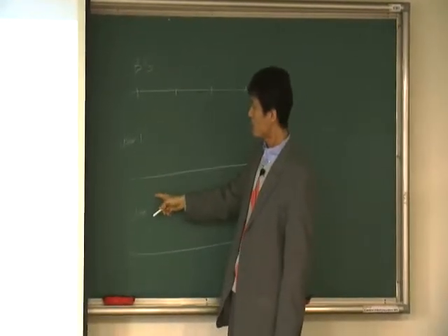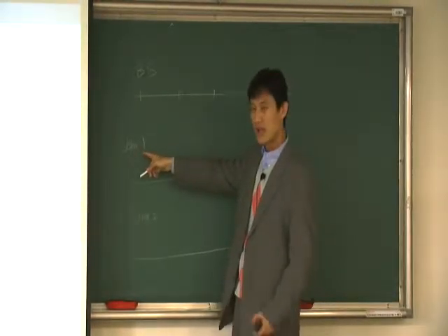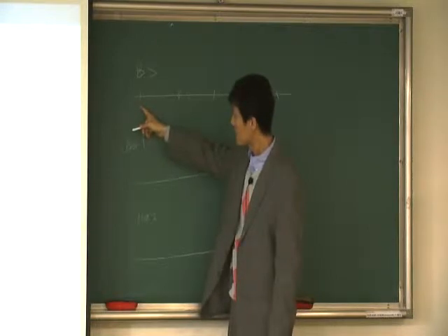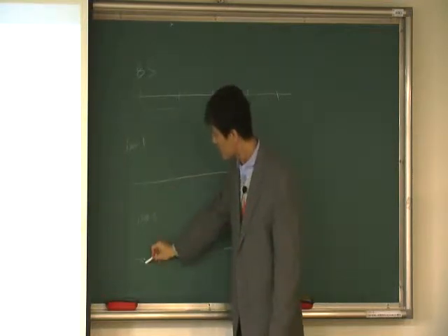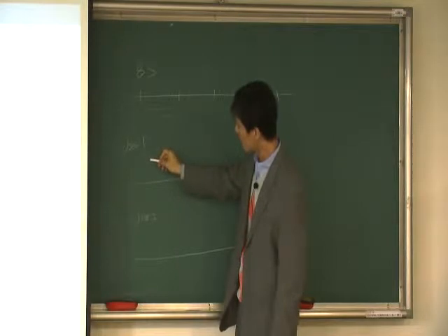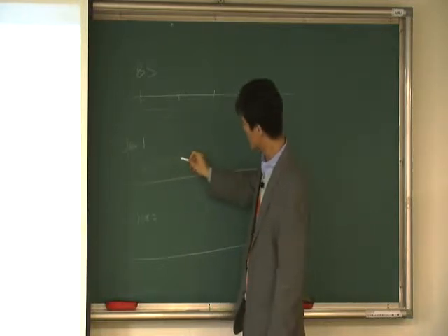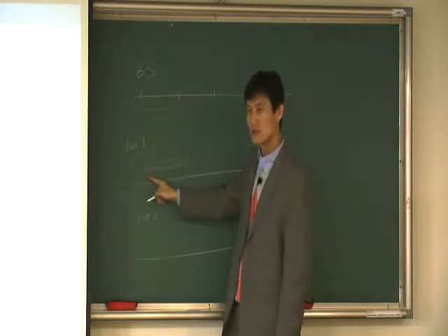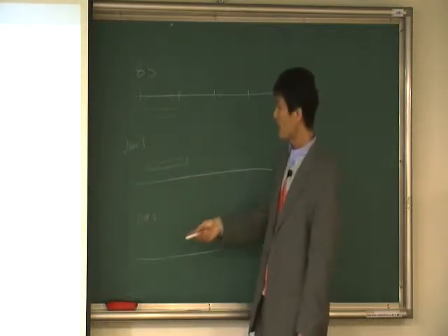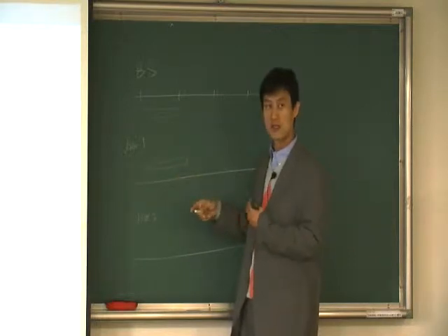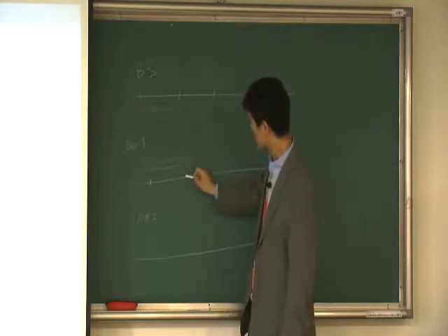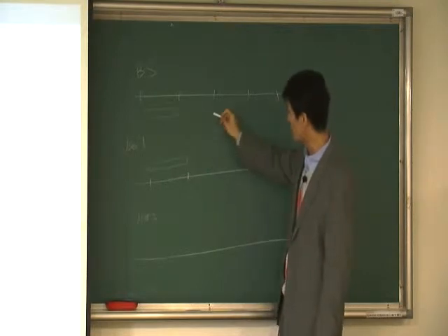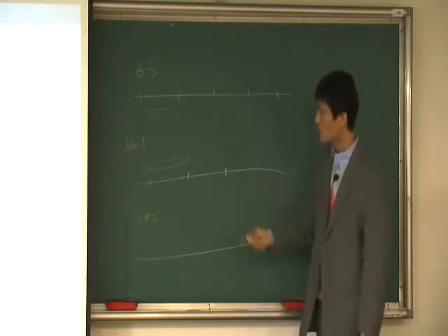However, from the user, the first thing to do is the downlink synchronization, where the base station transmits some packet like this, but the user 1 is close by, so the propagation delay is small. So user 1 will receive this synchronization packet a little bit later, like this. And this much is propagation loss, right? And once you get this synchronization packet, now the user 1 understands it and tries to make its downlink timing synchronized with this. So now user 1's downlink timing is like this. This is the user 1's downlink time.